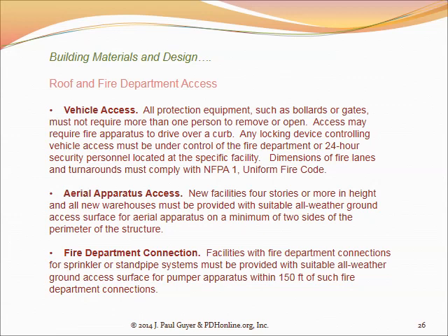And in the event of a fire, the fire pumper truck will drive right up to the edge of the building where this connection is, and they stretch out a hose to the hydrant in the street, connect one end of the hose to the hydrant, the other end to the pump in the pumper truck, and then the output from the pump connects to the vertical fire riser.